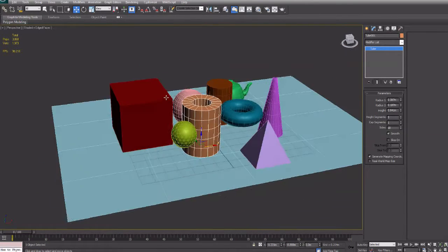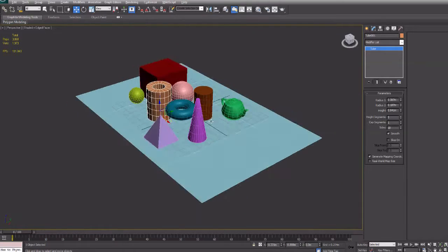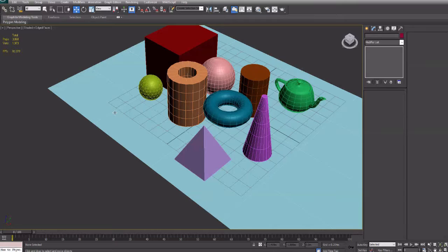The more polygons you see, the more RAM power your video card is going to be using. So as much as possible, you start first with as few polygons as possible, and take it from there. You go way up. Do not start with a lot of polygons first, then go down. That's going to be hard for you.